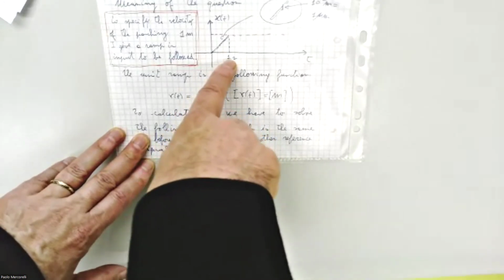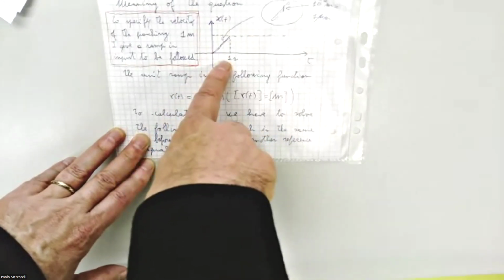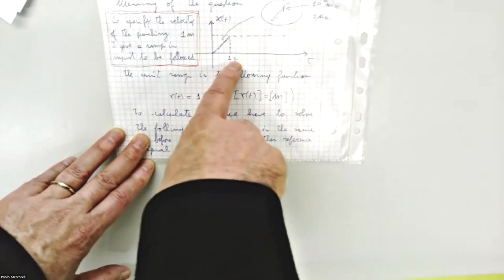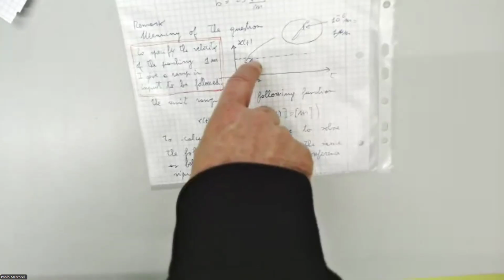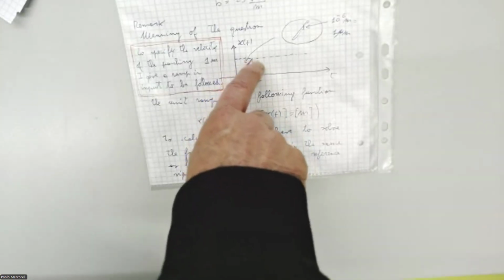The last time I told you how I can specify this Ki, for instance, saying that I want to achieve 1 meter in 1 second. I will repeat at the end of the lecture next week. Now, what happens? I guarantee that I reach 1 meter in 1 second with Ki. But now the question is an extremely important aspect to discuss.